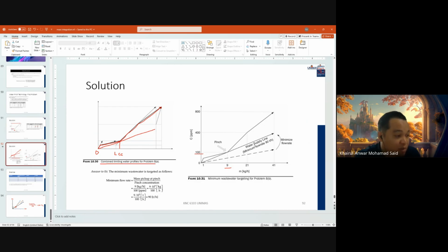So based on the process flow sheet, the plant needs 3 new piping lines to route the decanter wastewater to the scrubber, the new transfer pump, and the small intermediate water tank. So the estimated net capital cost is around 150,000, including the installation. So the payback period is 150,000 divided by 330,000 per year. It takes around 8.5 months, which is viable, by reducing the amount of fresh water.